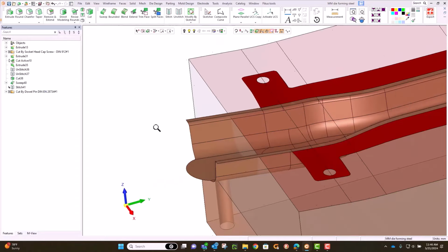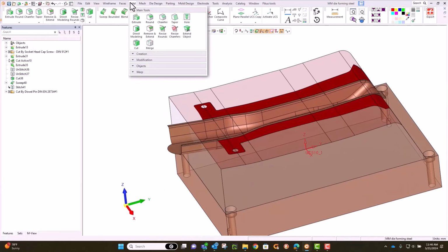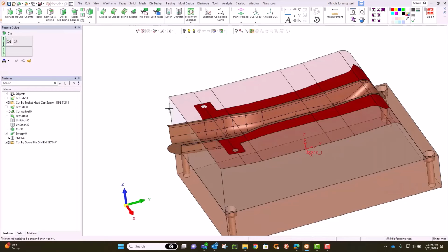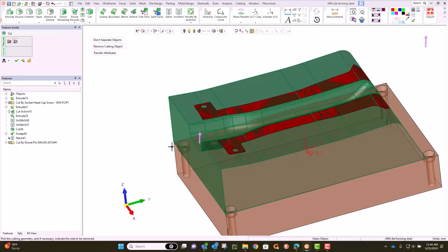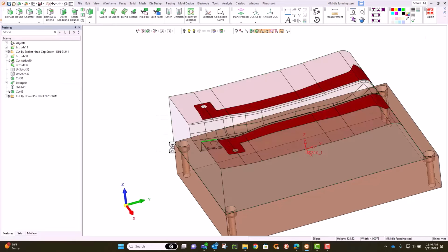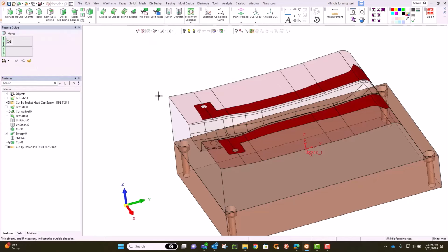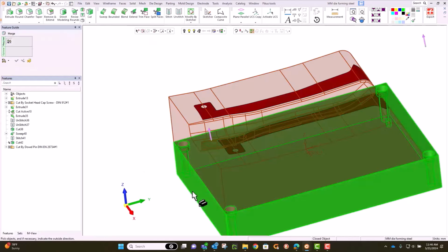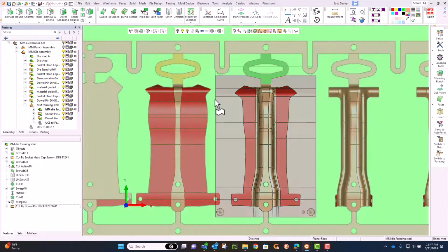We're going to now cut the block so that the shape of that trench is captured into it. Pick that entire object, and there it's cut in. I say, okay, there it is. So I've quickly got my form together. If that's what I want, I'll just go ahead and merge these 2 blocks together. And then going back to the assembly, the die assembly, I'd manipulate those screws so that I could get a longer screw where I need it. All good so far. So go ahead and merge it.